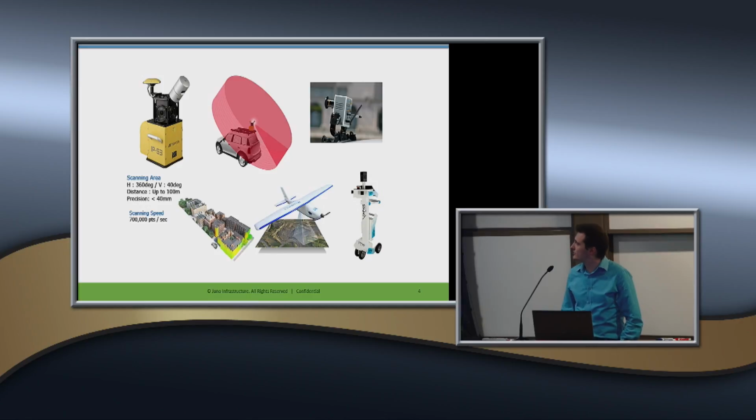Just a quick look at some of the tools that we've been working with. In the top left, we have a 360-degree camera with a laser scanner. Very similar technology to what you've maybe seen with Google Street View, but with the addition of the laser, you're able to reconstruct a 3D model up to about 100 meters if you're driving along your network with very, very high precision. So you'd use this if you need to do technical drawings, CAD drawings of your intersections, for example, and pinpoint accuracy of your assets.